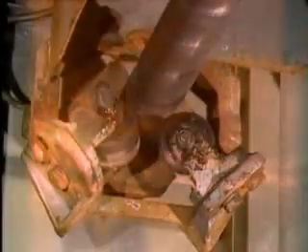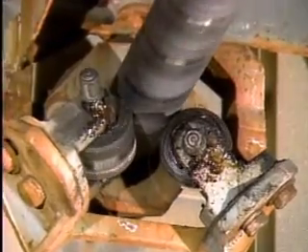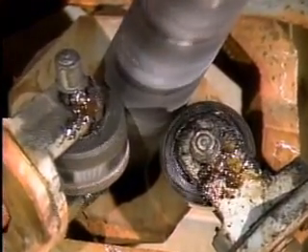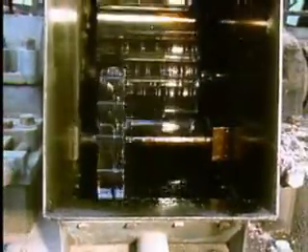The rollers support a device that's used to clean the tubes inside an operating boiler. Heat from the boiler is transmitted to the rollers in the grease. Grease made with ordinary thickeners would melt and drip out of the bearings, but the bentonite resists high temperatures, so it keeps the grease from melting. Many substances that are added to lubricants are liquids rather than solids. Some of these additives reduce friction under conditions of extreme pressure, such as between gear teeth.